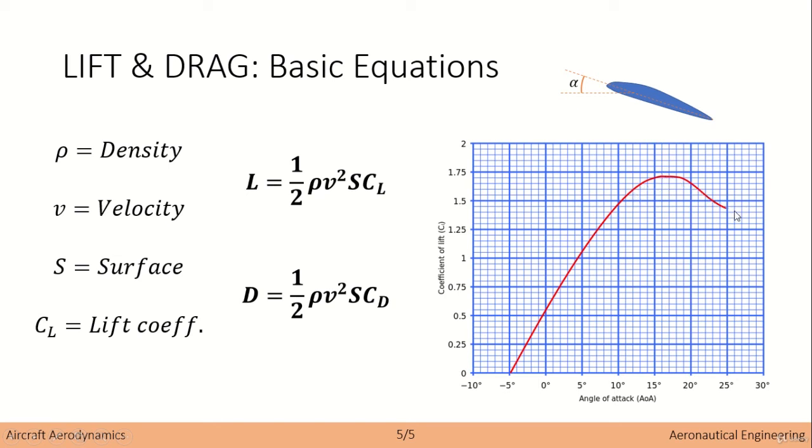We'll explain this better in other videos, but the idea is that if you continue to increase the angle of attack, then you would actually have stall. If you have a very high angle of attack, you would have high turbulence on this part of the airfoil, and therefore you would not be able to transform the velocity into the difference in pressure, following Bernoulli, right?